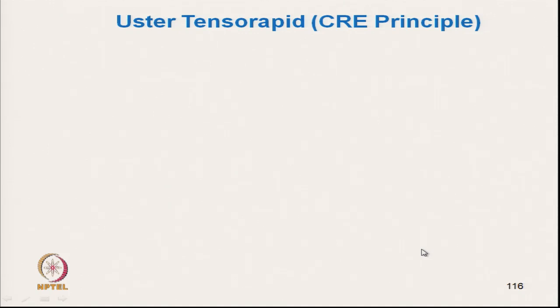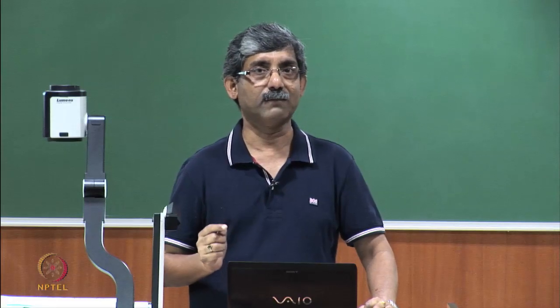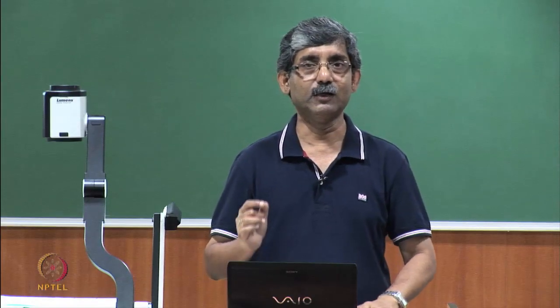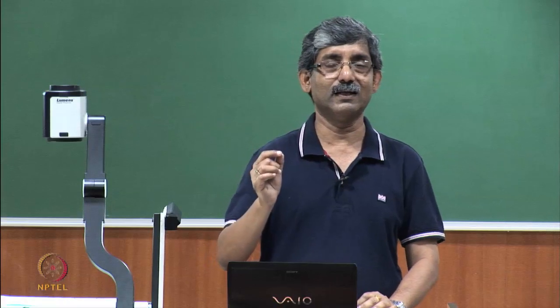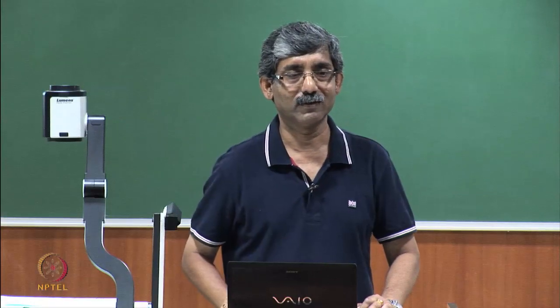So, the last segment we have reached here gives us another instrument which works on the CRE principle. The principle is the same as that of single yarn strength testing, but this is fully automatic. In UTM, when we test single yarn strength, we put the yarn in the jaw manually, but here